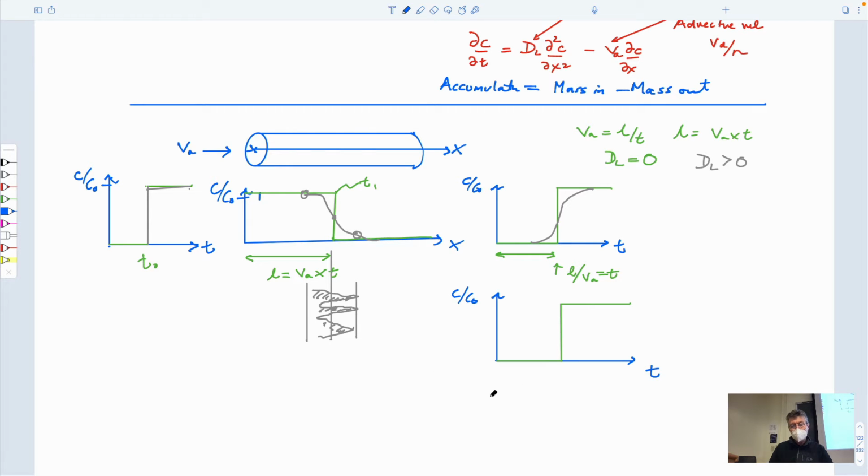And so in real systems, this plug flow behavior and this steep front with the 50% concentration in the middle of this length is only true for Peclet numbers, which are advective velocity, length over diffusion coefficient, greater than about 10, I think we said.